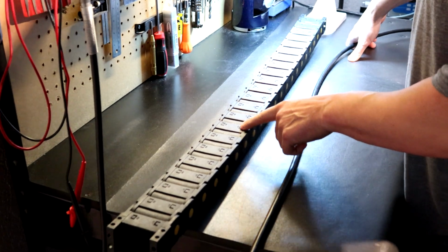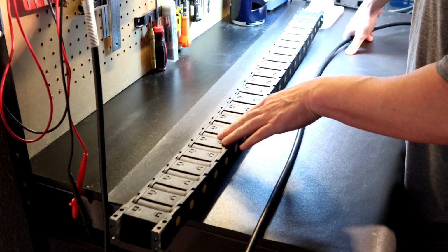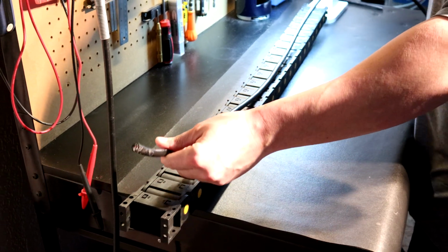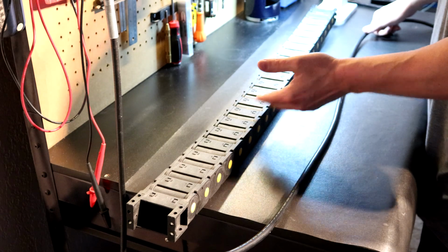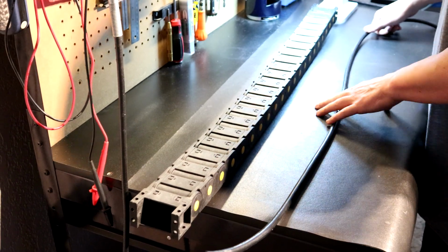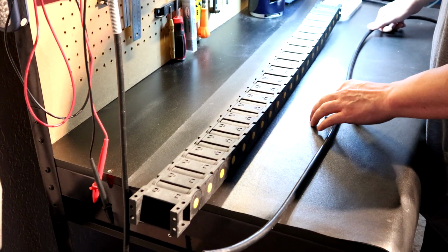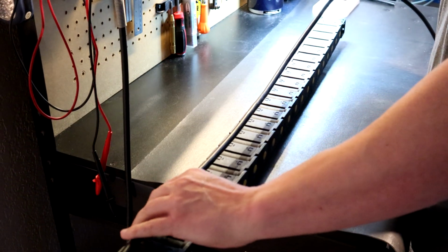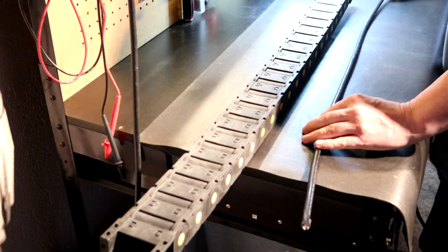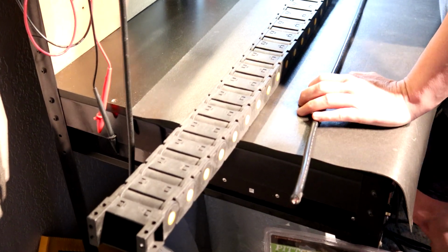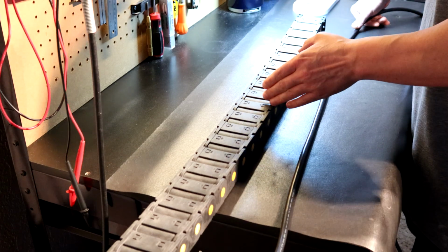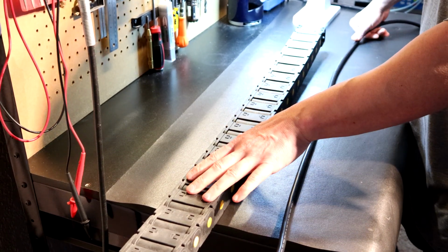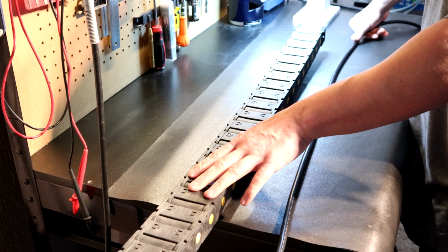The first option is to disassemble the actual links in the chain and actually insert the cables into it. If you do that, keep in mind, you got a lot of work ahead of you, okay? A lot of guys are not going to do that. Most guys, what they're going to do is take the chain and just generally insert the cable into the chain. They do that with all of their cables. If they do that with all their cables and you have any pinching going on, you may not see it. So again, up to the end user on how they actually assemble their cable chain.